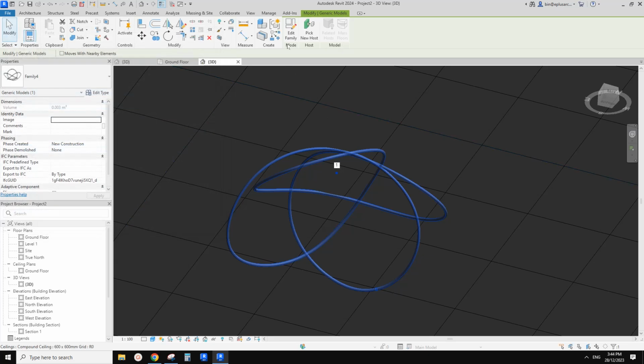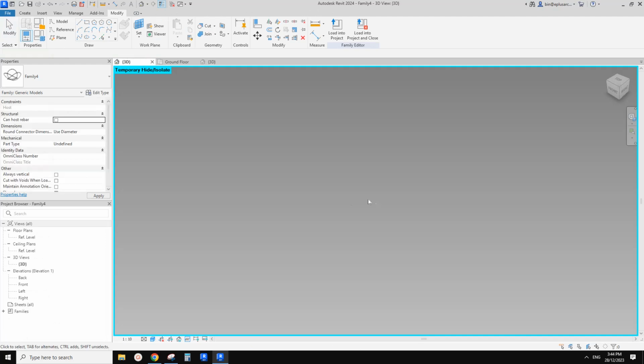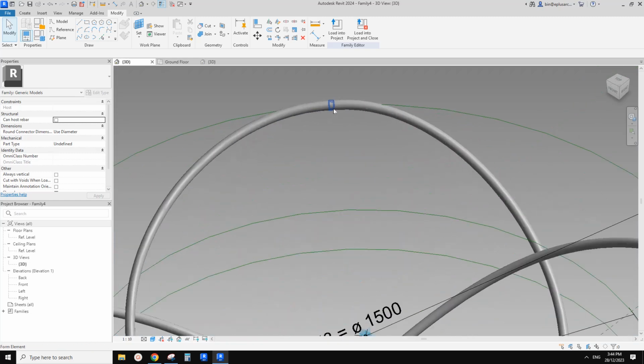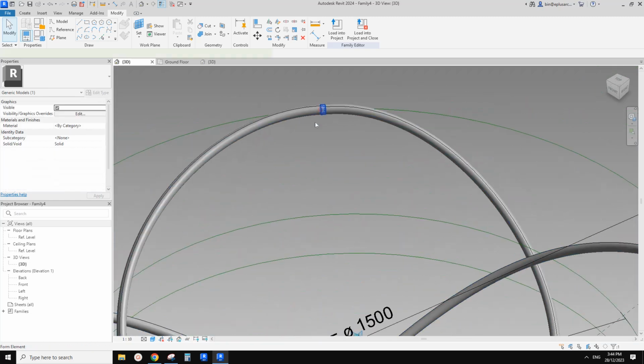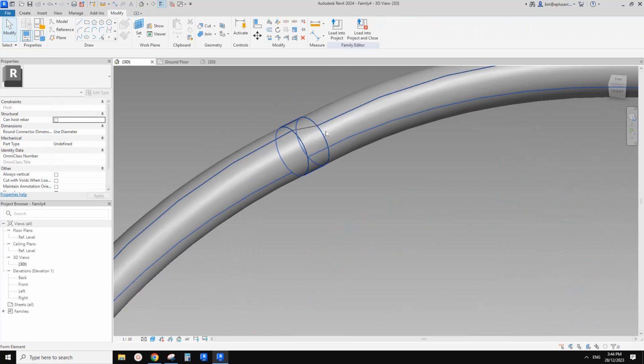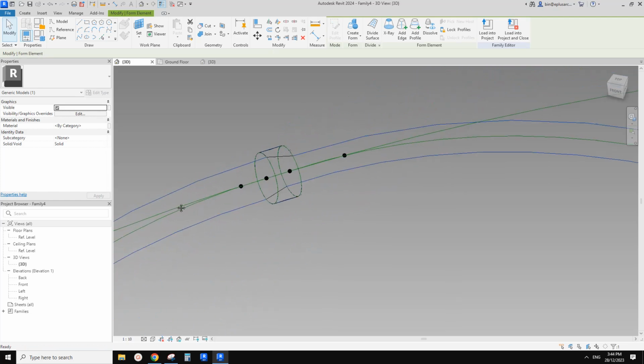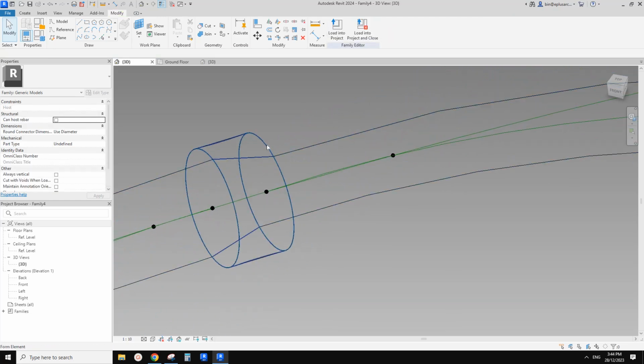And also let's quickly go back to the family. Maybe we can, so first type HR, so we can also create a parameter for the radius. So let's type WF, select this profile, so we need to select, try to tab until you pick the reference line there.